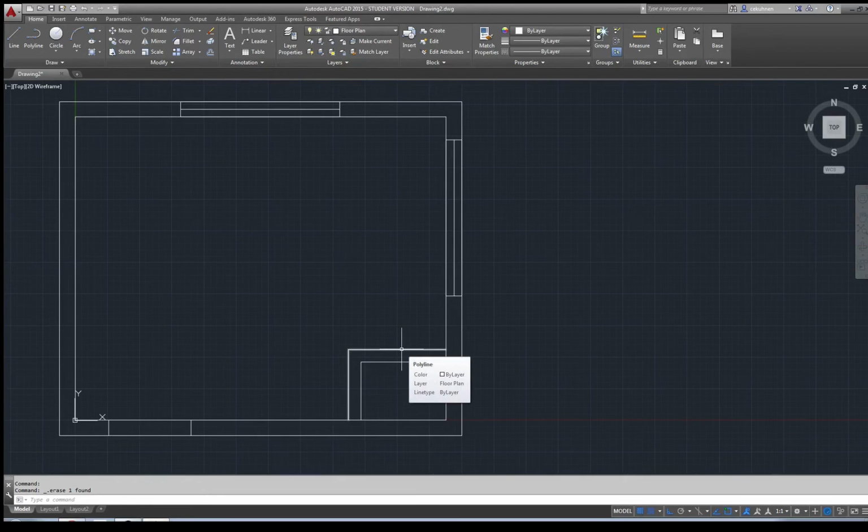Now, when we are taking a look at this one, there are actually two ways we can create or continue working on a floor plan. And this is actually already an important stage for pre-planning our three-dimensional model. Now, this is an exterior wall, and this is actually simple drywall that was created inside. It's not really connected. So you have an option to either decide you would like everything to be one floor plan, so those lines here are gone, it's all joined, and then we can extrude it once. Or you could say, well, I would like to have this wall extruded and this wall extruded as a single object.